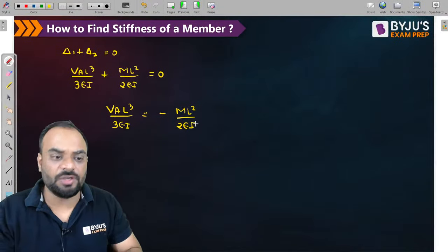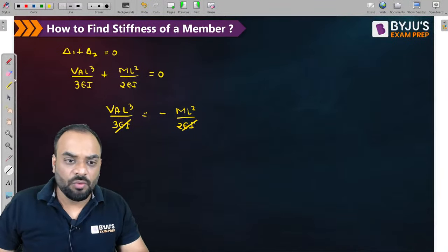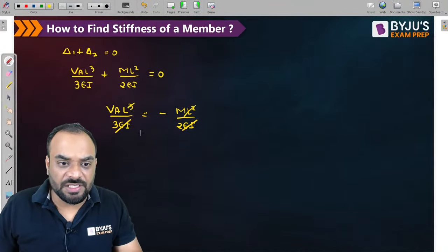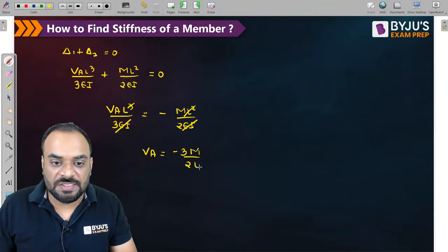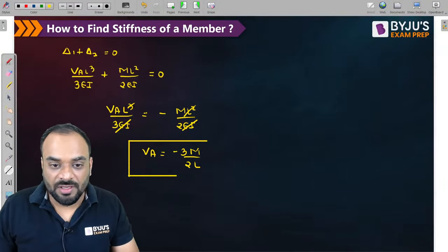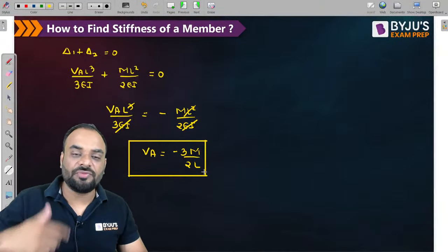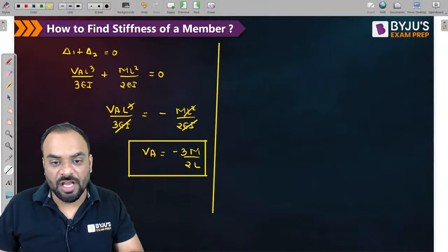Guys, if you are not able to understand anything, please let me know. I will explain once again, or I will explain whatever doubt you have. Okay. And you can cancel this particular value easily. So ultimately you will get the value of VA, and it is equal to minus 3M by 2L. So this is our VA reaction in terms of M. Now the question is, sir, I need to find out the value of theta A, or the stiffness of this particular member at support A. How can I do it?